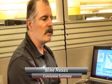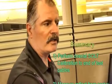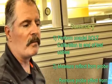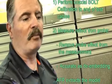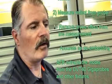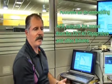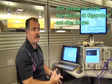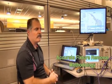And so, in conclusion, what we've shown is probing with a VNA and driving the automatic fixture removal technique with physical layer test system software, we're able to first do a coaxial calibration to the end of the test cables, and then, by just simply looking at a reflect of the probe, we're able to remove all of the probe effect, which is just as accurate as de-embedding, because AFR allows us to extract the S4P information of the probe, which is the model. And so this is a very accurate methodology.